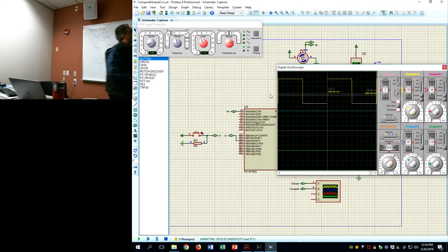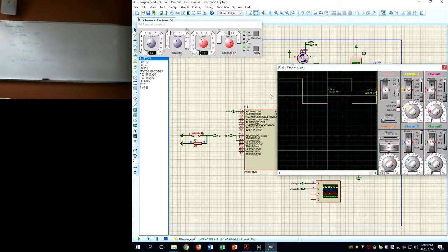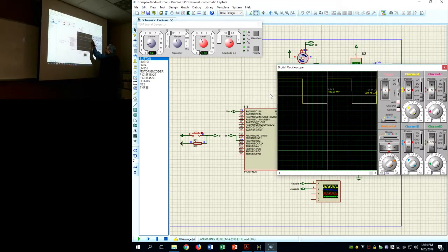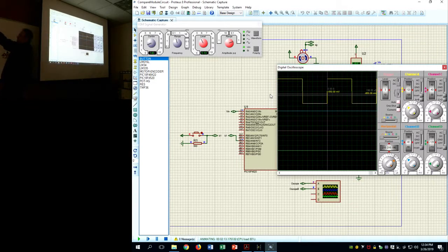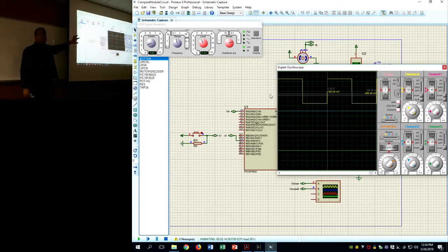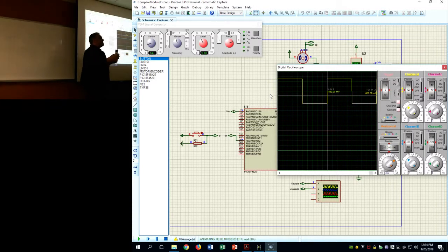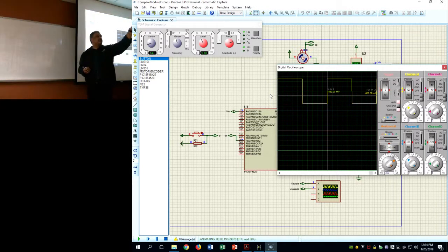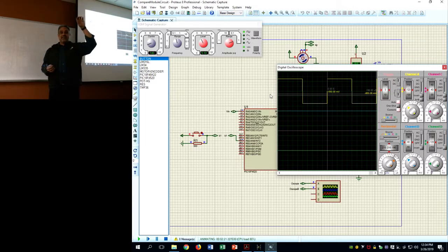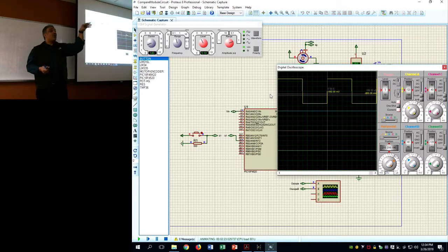Look at it. I don't know if you can see it because it's very tiny, but that's 0 seconds. That's 198, and I'm not quite on top of it. If you notice, my white line is a little bit off. I couldn't quite get it with the mouse, but that's 200 microseconds. So if you take a look at my math, I can actually perfectly predict what the oscilloscope will tell me. See that? And so when it comes to delivering devices to the Food and Drug Administration for medicine, these interrupts are so accurate that they pass all the FDA testing. That's why we use these guys.